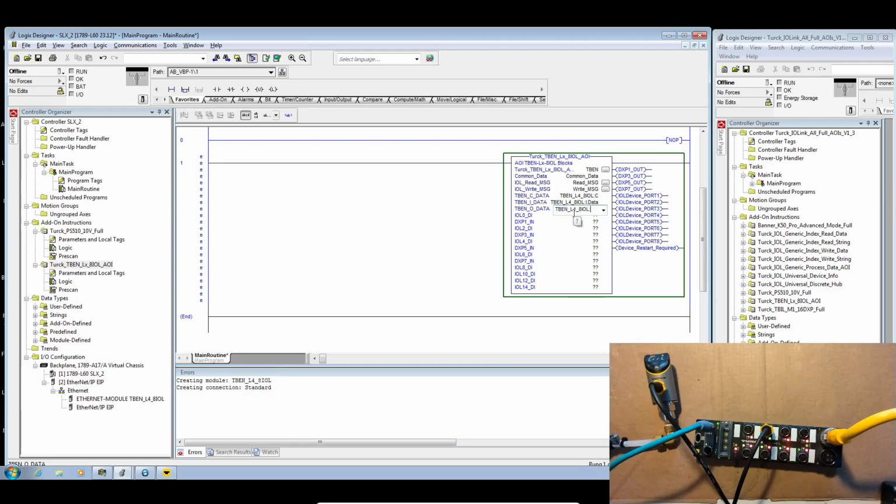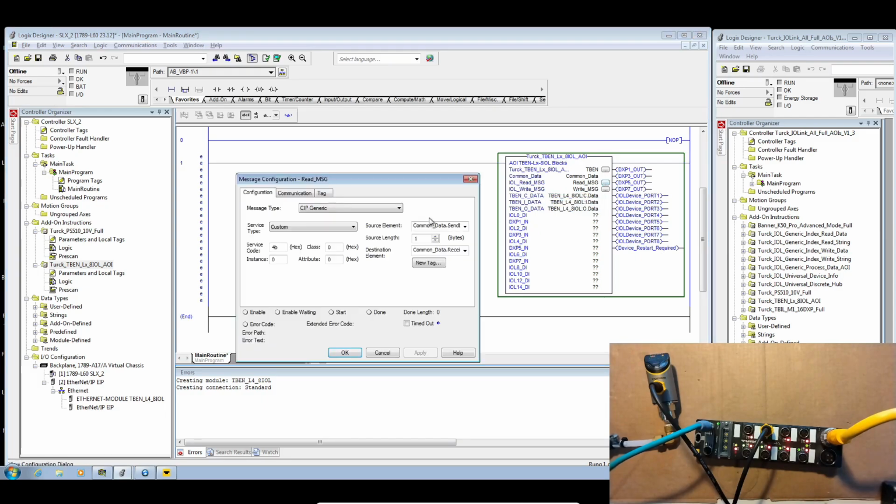And I'm going to point the AOI to the controller tags of the I/O block that we're going to control. So we're going to just O.data. Okay, and then we also need to change this to C.data. Now, the message instructions need a little bit of setup. So each one is going to be identical.